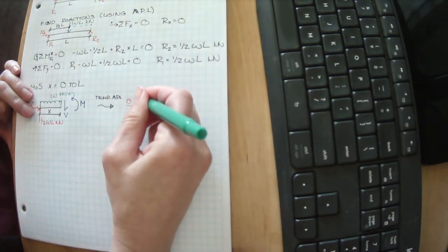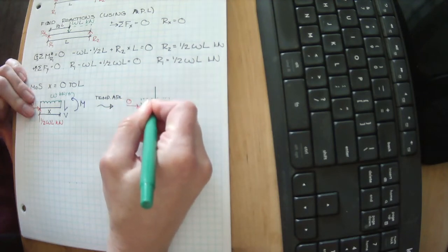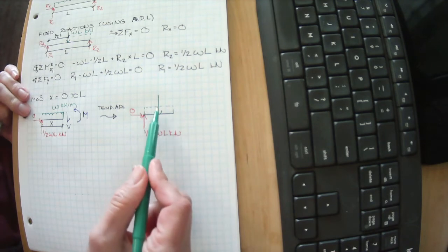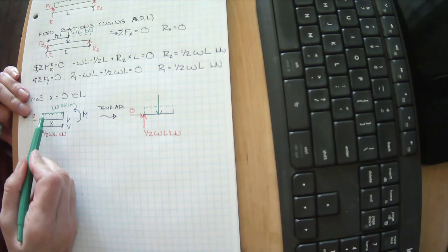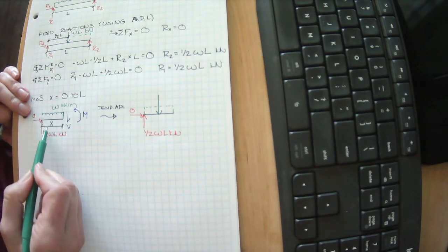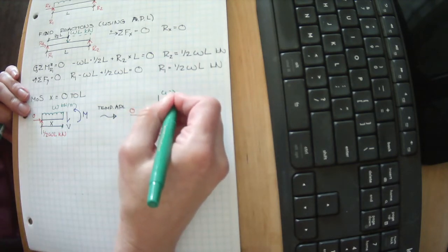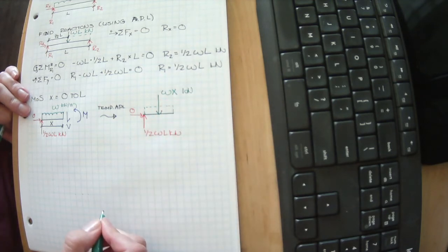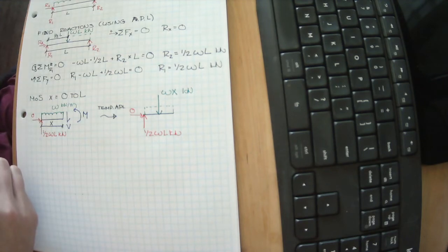And we are going to turn this W value into an analogous point load. The value of this is what was under this curve, really. Or we're saying for every meter length, we have W kilonewtons. The length we're using is X here. So the value of this is WX kilonewtons. Okay, so that's how long this portion of load was.